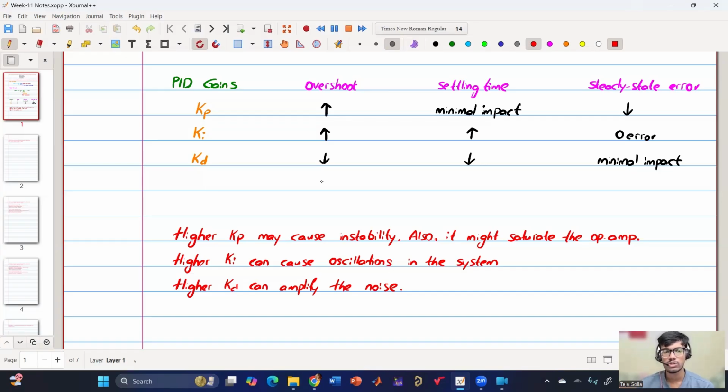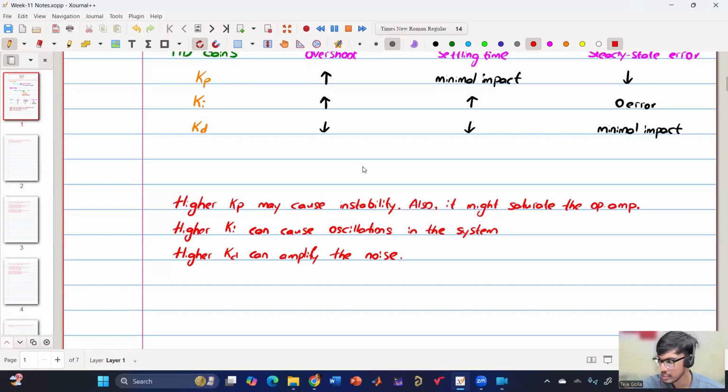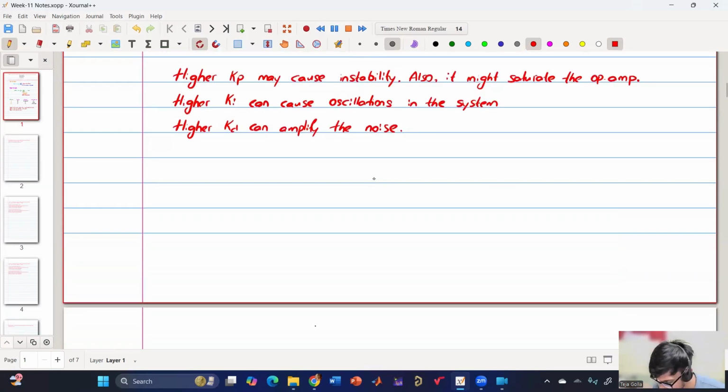Then we can fine tune the gains around the gains that we have obtained using the design, and then we can make sure that the system is performing in the way that we need. So now we can use this knowledge to fine tune the KP, KI, KD. But first, what we have to do is model the controller, sorry, model the system, and then design the controller.